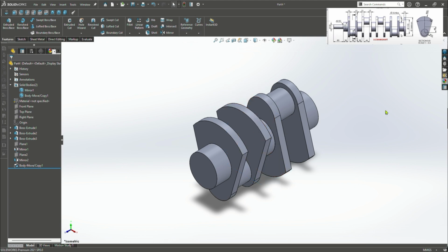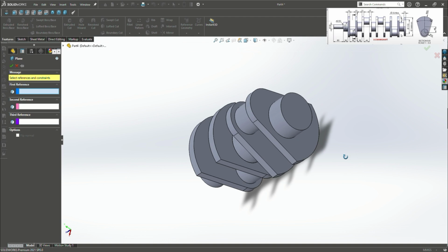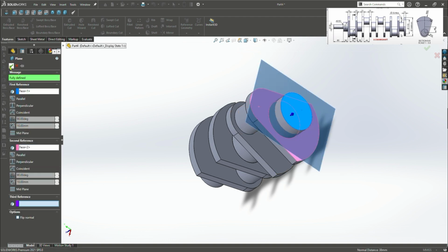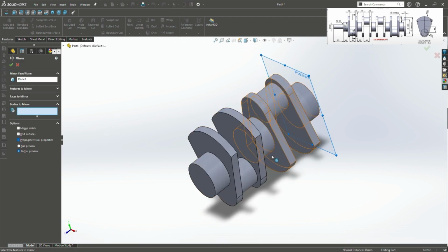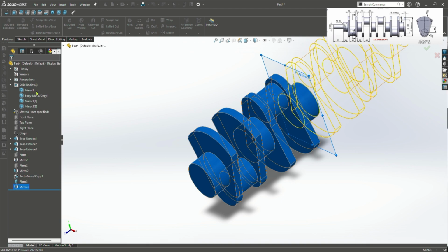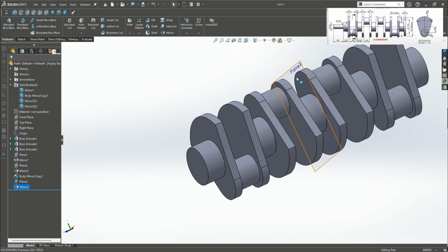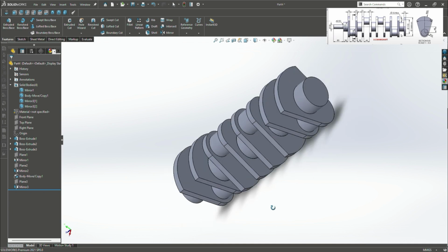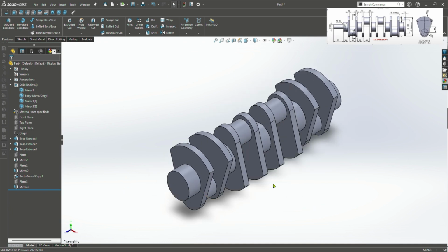So hide the plane 2, add another reference geometry just like before. Choose 2 and bodies to mirror. Okay, there's 2 piston that will go up and 2 piston will go down by this crankshaft right now.